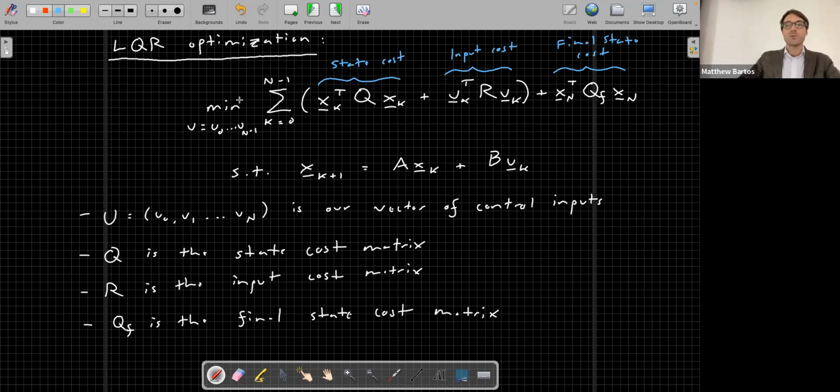Okay, and the LQR problem is to find U, the collection of inputs over each time step that minimizes this problem. So we can write U is equal to argmin of this optimization problem, where at each time step it's constrained by the LTI dynamical system. Okay. Are there any questions on this setup? Any questions on this optimization problem? Okay, so as I mentioned before, LQR is balancing between deviations from our reference state and input energy usage.